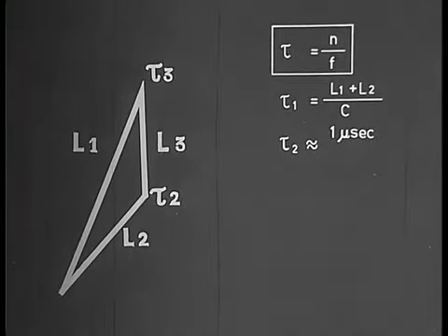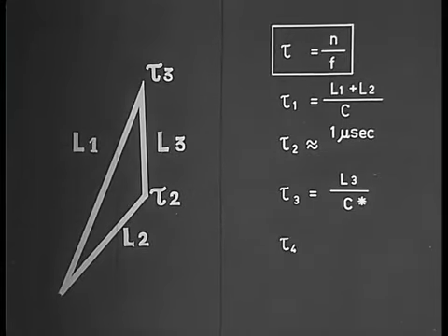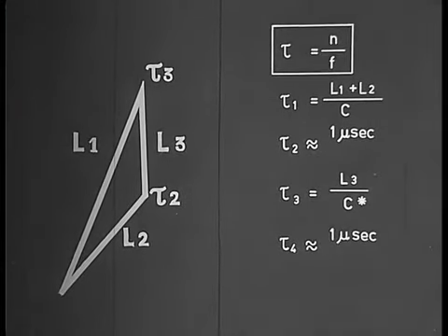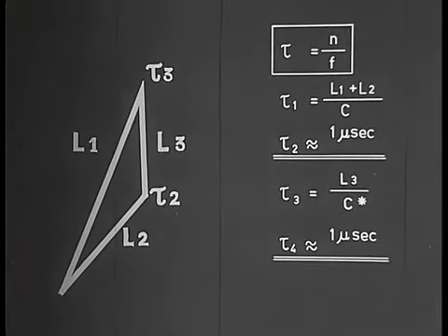Tau 3 is the time needed by the vortex to reach the original sound source. Tau 4 is the time of interaction in which a new sound pulse is generated. Tau 1, Tau 2, Tau 3 and Tau 4 were deduced from the photographs. Tau 2 and Tau 4 were found to be of the order of a microsecond.